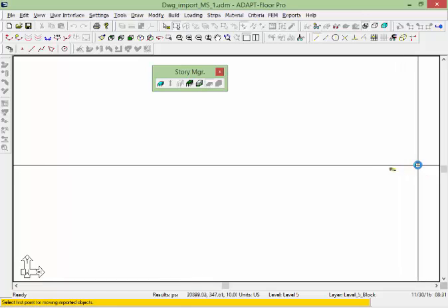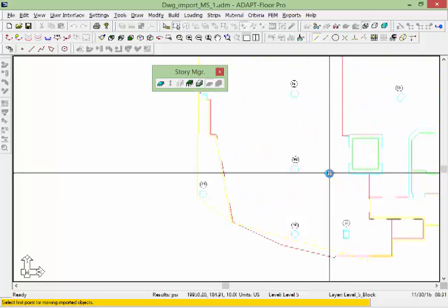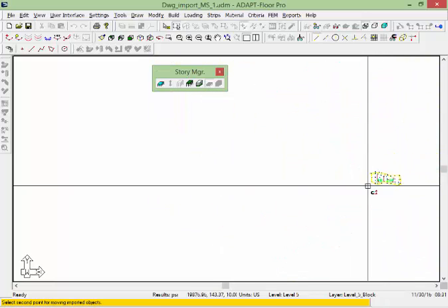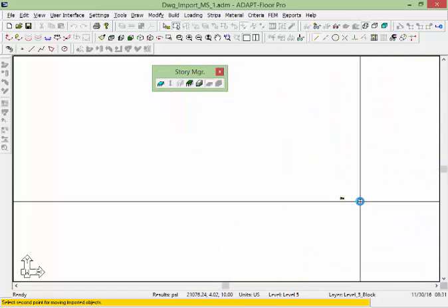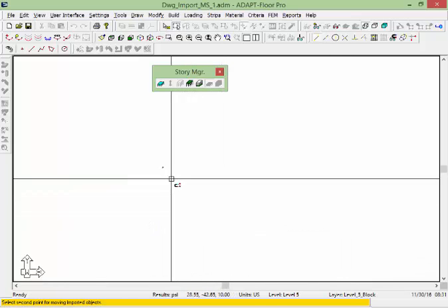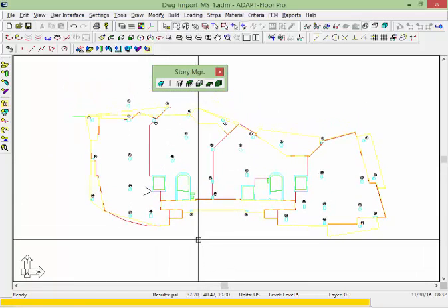So we want to get that back into a location that's reasonable, and I'll just use this corner of the wall group, which stacks vertically through the building, as my reference marker. So we'll select that point, I'll come out here, and I'll move that into position where I had my reference point, which was here. And now we're ready to transform these lines into structural components.